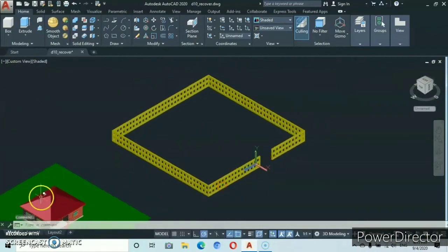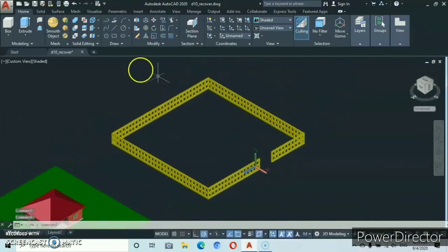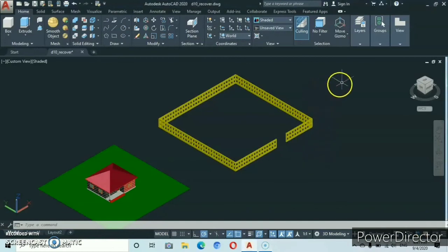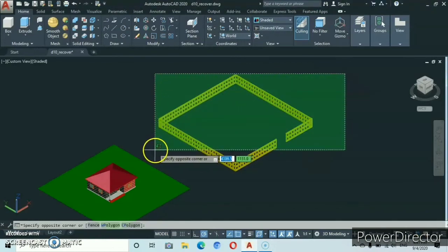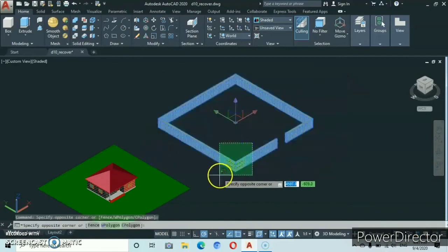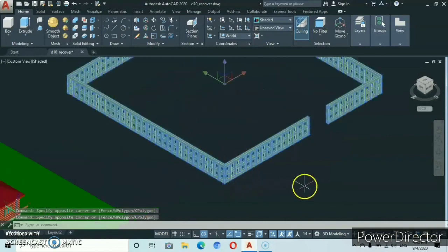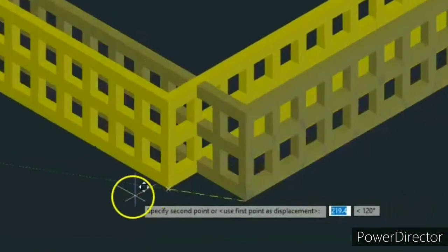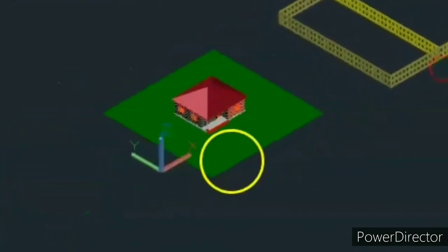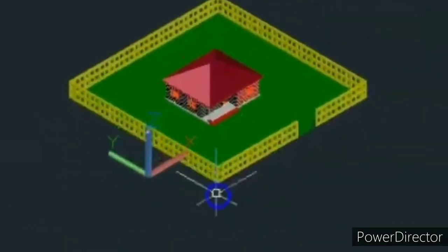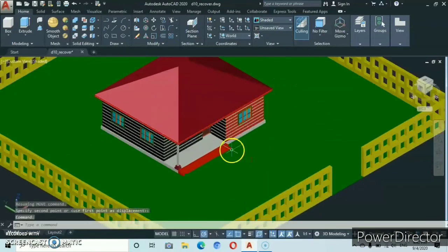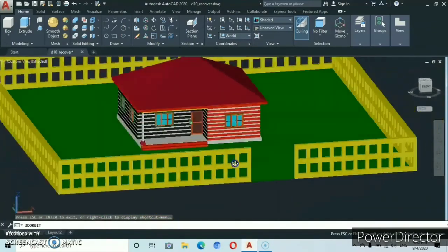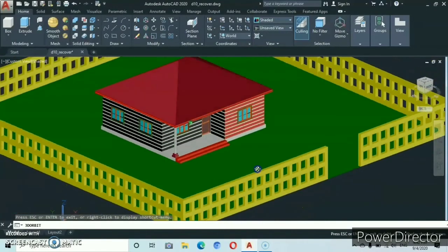Okay, from here now we can move this fence to the building. So we select, let's go back to the wall coordinate. Let's carefully select this fence. Okay, careful, select all the paths. Then now we go to move command, you move at this end, move right here. Then let's come here right at this end point and we click there. Now you're gonna see something like this. Let's try to orbit to see what we got first. Yeah, so we're gonna have something like this. Okay, very good.